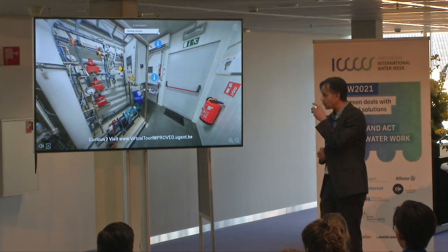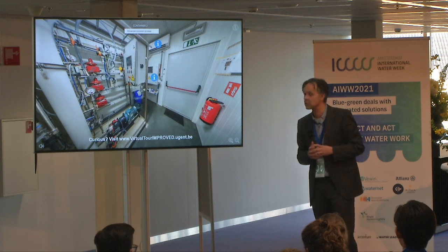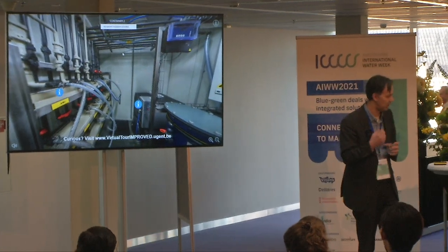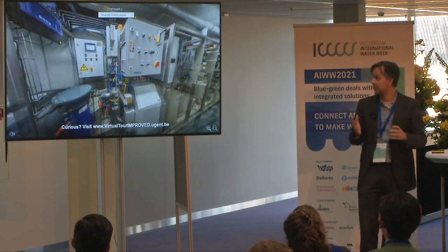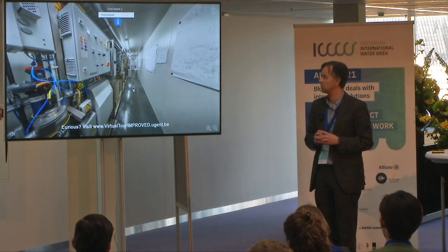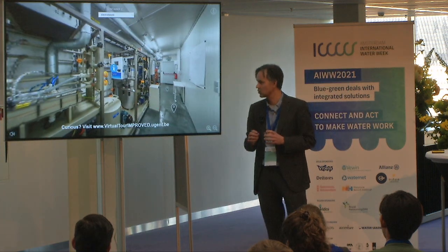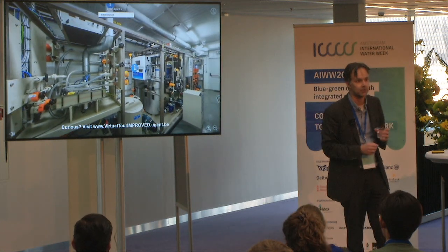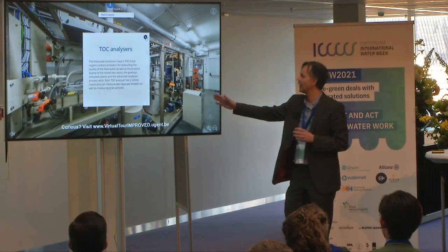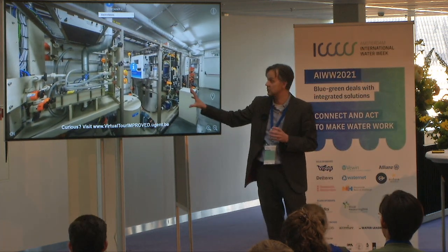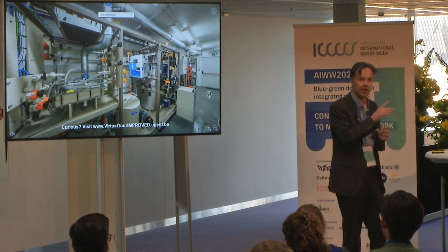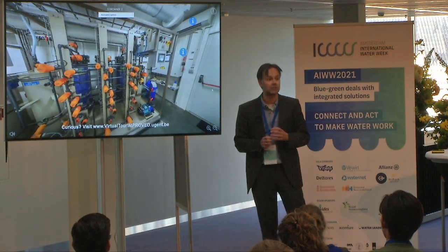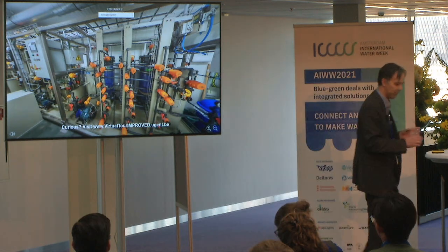Going to the other container, you see advanced oxidation processes, in which a UV peroxide process, so a peroxide injection system, and the UV reactor to manage advanced oxidation processes, electrodialysis. That's also a membrane process with charged membranes driven by a potential difference over the different alternating membranes. Also online TOC analysis, because for condensate treatment, TOC is a very important parameter. And to follow that online, we use this analysis. And finally, we have the activated carbon unit, all in two containers, mobile.